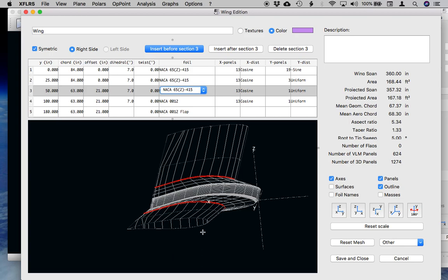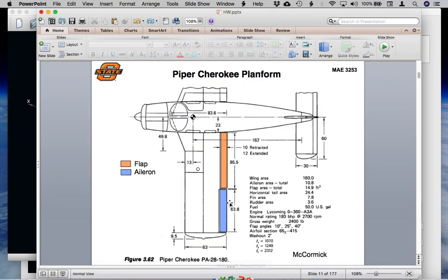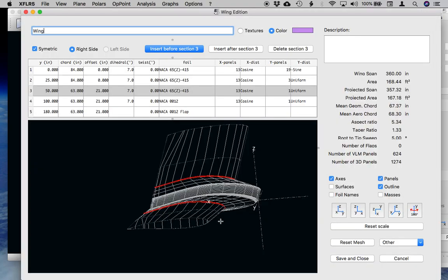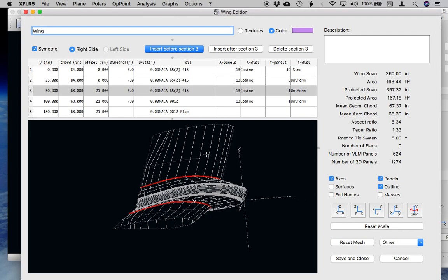So you'll need to create these airfoil sections with that correct geometry for the wing, indicated by the locations of the flaps and the ailerons respectively, with the flaps deflected at 10 degrees and then the ailerons deflected at either -5 or 10 degrees for the port and starboard wings, and then come back in and rerun that.